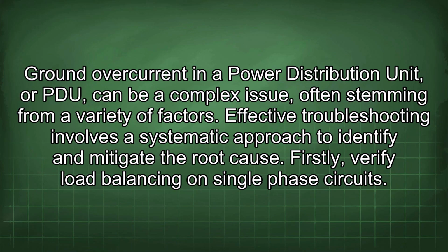Ground overcurrent in a power distribution unit, or PDU, can be a complex issue, often stemming from a variety of factors. Effective troubleshooting involves a systematic approach to identify and mitigate the root cause. Firstly, verify load balancing on single-phase circuits.